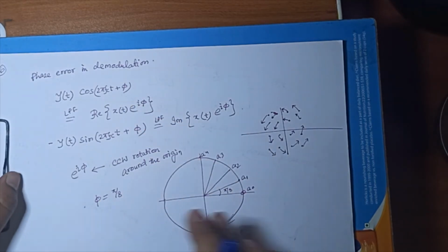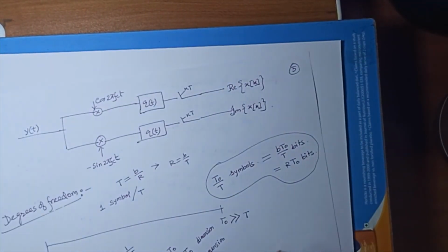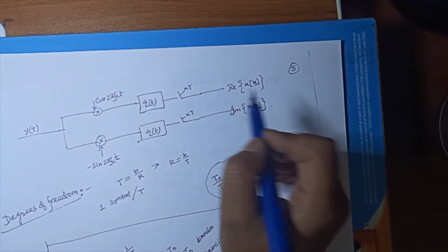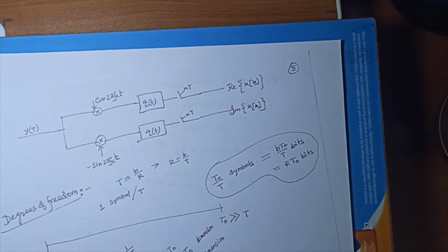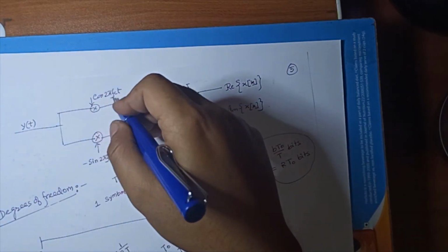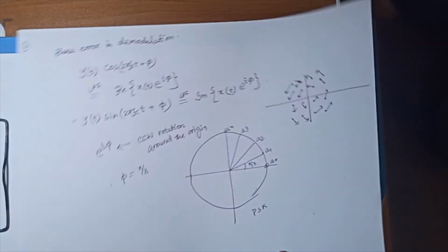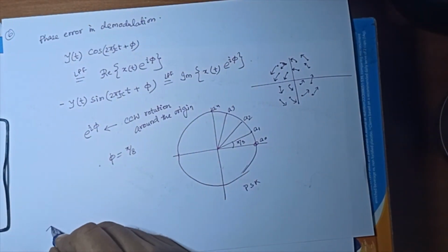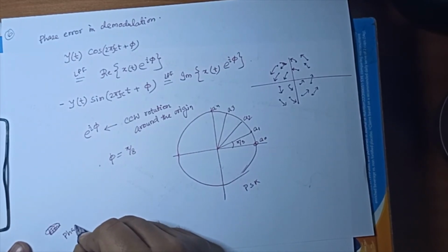Second thing is the sampler. Of course, unless you can sample it properly, you are not going to get this. So the clock has to run in the perfect way, and these local oscillators have to run in the perfect way. This entire business of timing recovery or synchronization is an enormous task. So I can talk about timing, phase and clock recovery.